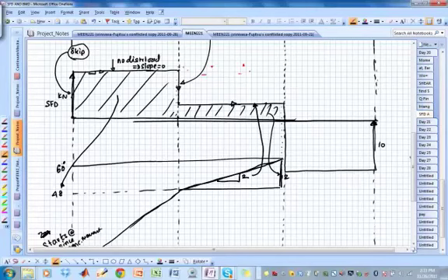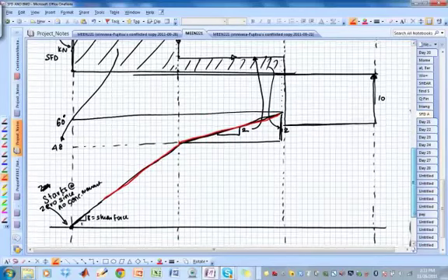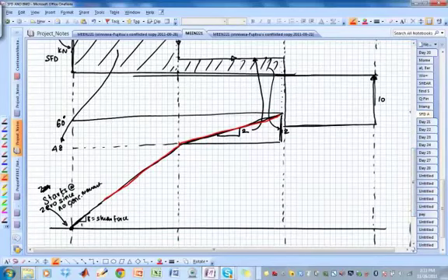Now what happens? Can you see that the slope is negative? So it's going to come down. I'm going to draw this in a different color so you can see. So there's the bending moment. I told you we need more space, right? See, I almost ran out of space. So I want you to understand that if you're going to draw the bending moment diagram to scale, you will need lots of space. And then I'm going to come all the way down. I know it will hit 0. So I'll go like that. The slope will be negative 10. That's this height.